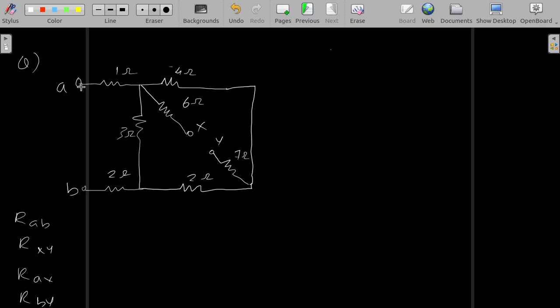So when we are applying this current across A and B, what happens? Current will flow like this. At this point, how will the current split? It will go through here. It will go through here. Will it go through here? No, it won't. It won't pass through this branch. Why? Because it is an open end. Current always needs to go back to its original point, right? So here it is what is called an open circuit. Current cannot jump from this point to this point. So whenever the current reaches here, it cannot flow through.